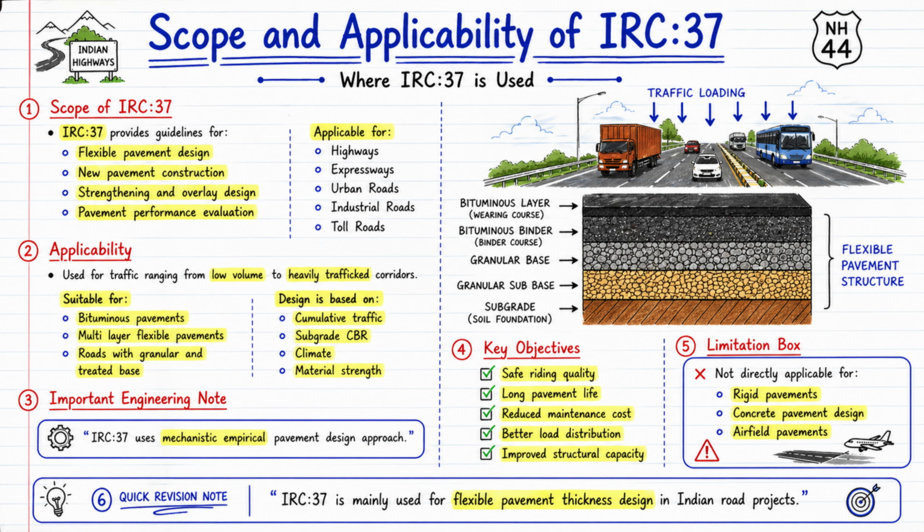Pavement performance evaluation. Now the fourth point, pavement performance evaluation. That is, how is the existing pavement performing? In that, how much is rutting, how much is cracking, how much is remaining life. The evaluation of all these things is also related to IRC philosophy.